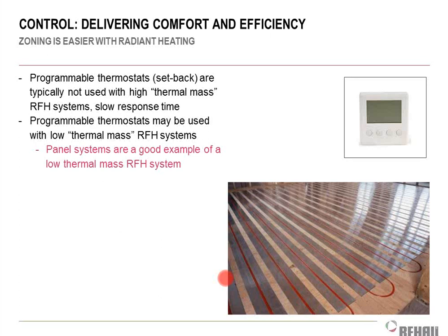There's a couple of reasons for that. From an energy standpoint, you're already getting a boatload of energy savings because you have a lower thermostat setting, right? Matt keeps his at 62. I keep mine at 69. He's going to spend less energy to heat his house. If his house is 62 degrees, the heat loss from inside his house to outside is less than mine on a 0-degree day, right?